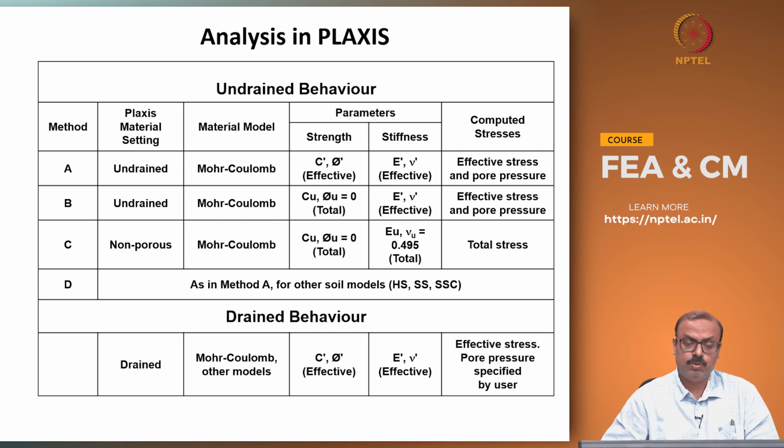If you choose non-porous, there also you can do undrained analysis. There, everything will be total stress: the stiffness, the strength as well as the output.